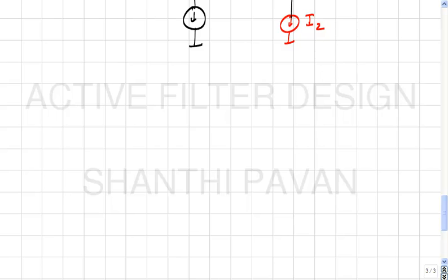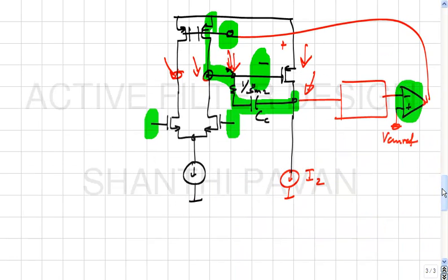Two identical op amps: if I yank the common mode of one, let us say the output common mode goes down, right. If I put two in cascade, whatever the sign of the common mode gain is for each of the single stages, when you cascade two, the end to end gain will always be positive, correct. So if I now had two integrators like this hooked up in a negative feedback loop for differential signals, it does not help me that there is negative feedback for differential signals, because for common mode signals there is positive feedback. And you can see that this is a disaster waiting to happen, right.